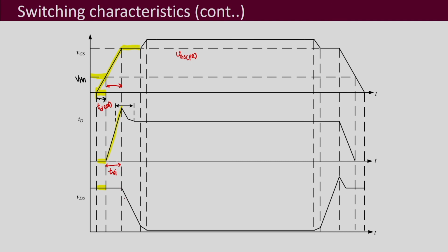After that, the voltage tends to decrease, and the gate to source voltage over here remains constant, it is not increasing. One thing you also notice here is that before this, when it is going from threshold to this Miller voltage, although the current increased, and it actually reached a value greater than the on state current value, the drain to source voltage did not change at that time.